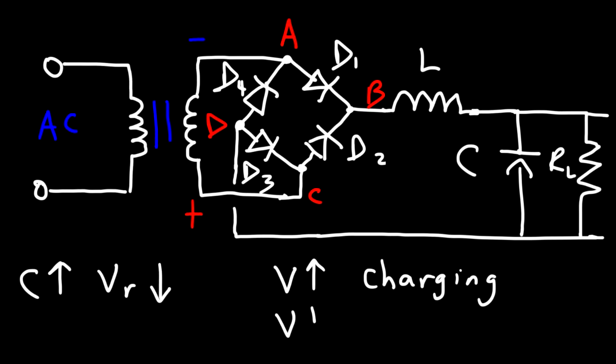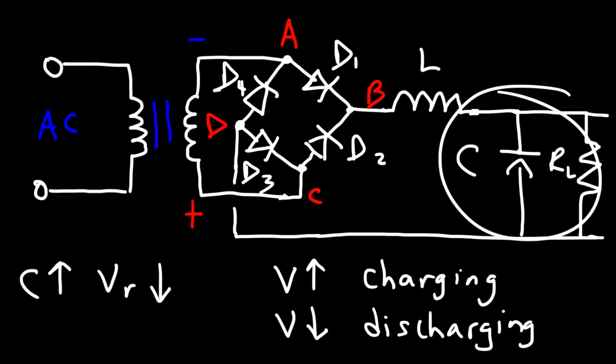And when the voltage decreases, we know the capacitor will be in discharging mode, releasing energy to the circuit, thus supporting the falling voltages. So basically, putting the capacitor in parallel in this region allows the voltage to be held constant. When the voltage goes up, the capacitor will store energy in its electrostatic field. And when the voltage goes down, the collapsing field will release energy, thus maintaining a constant voltage.